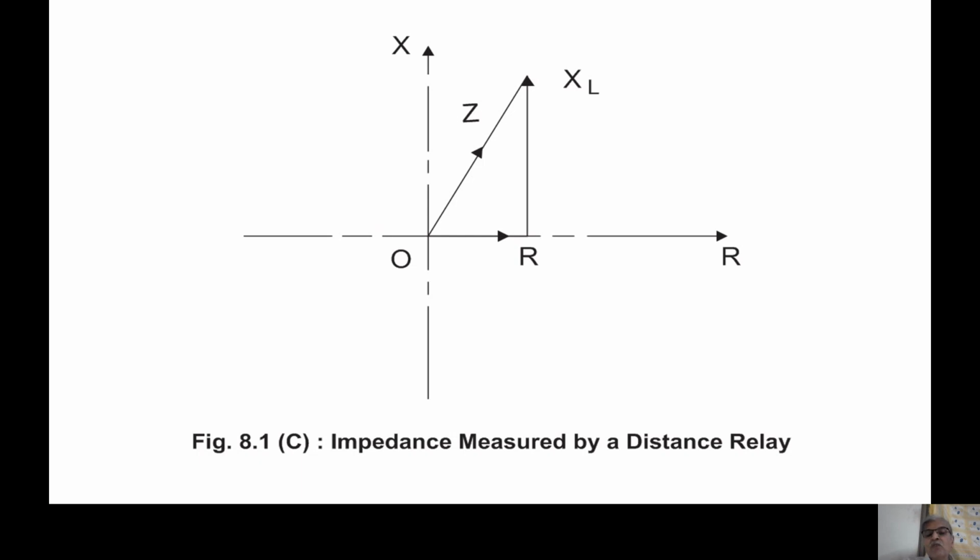If I am talking about resistance and capacitive reactance, if there is a long line, and obviously there is capacitance, and nowadays people connect shunt capacitance at the receiving end to improve power factor, then in light load condition, with R and XC, that Z will lie in the fourth quadrant, right? So that is the fourth quadrant.